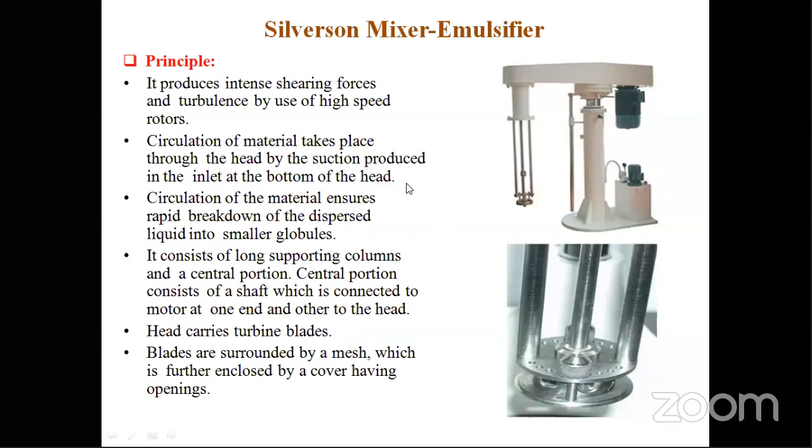And during circulation, it creates some amount of pumping action which creates suction. And what is the function of the suction here? Whenever you are mixing a liquid or emulsifying an emulsion, some amount of liquid settles down at the bottom. Suction helps to draw the bottom liquid into the upper portions. When it creates suction, the bottom liquid also comes to the upper side and comes into direct contact with the blade, so it is easily mixed with the other mixtures of the emulsion.